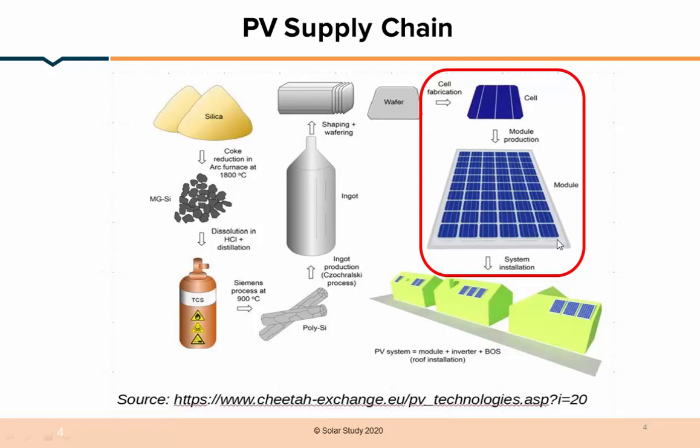By connecting all the cells, they should be protected. It is protected by an aluminum frame, encapsulation over the top surface, and then a backing material to support the silicon cells. Then there is a junction box which takes the two terminals. We know that all the cells are connected in series, with a plus and minus terminal. Finally, it goes to the junction box, where it is connected as a single positive and single negative.